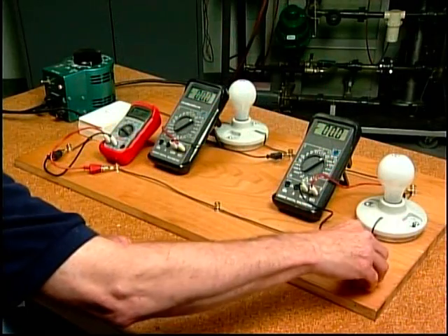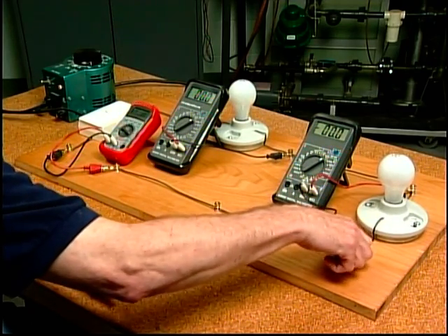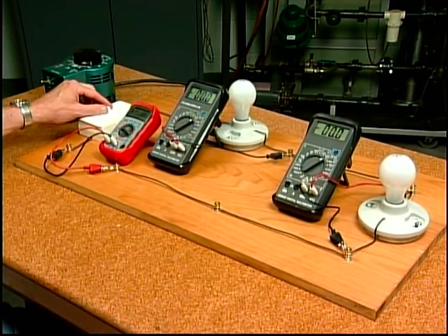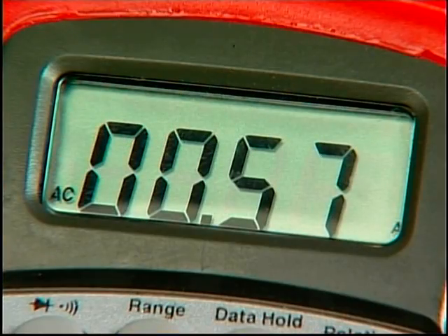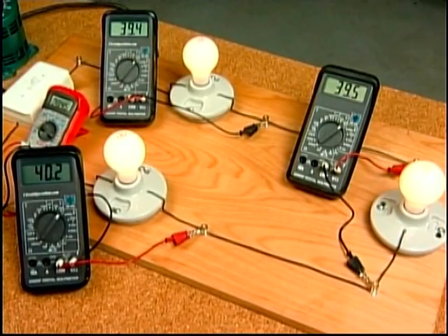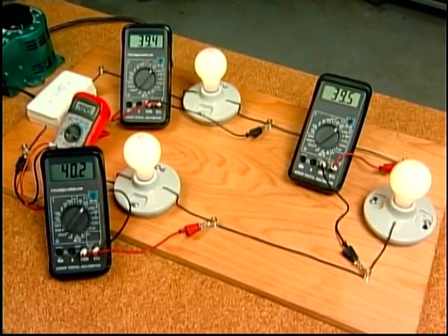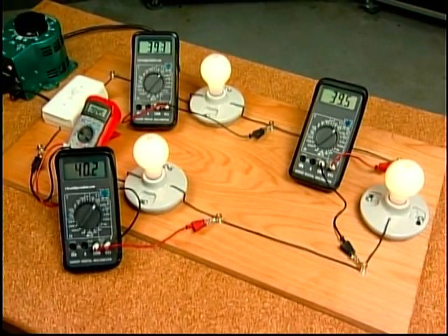This principle also applies to alternating current circuits, when a voltage drop occurs when current flows through a lamp or lamps. With two 100-watt lamps replacing the 10 ohm resistors and 120 volts AC being applied, the approximate half-amp current flowing in the circuit produces a 60-volt drop across each lamp. Adding a third 100-watt lamp decreases the total current further, resulting in a smaller voltage drop across each individual lamp.